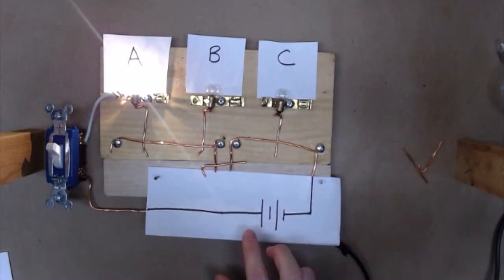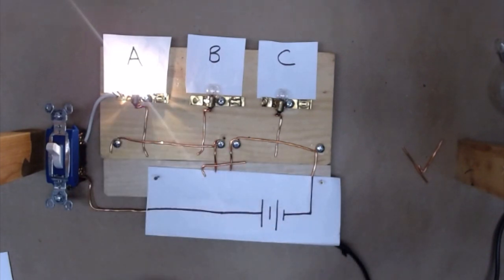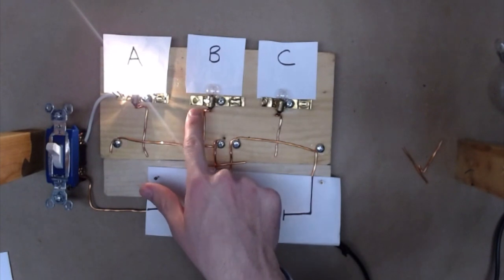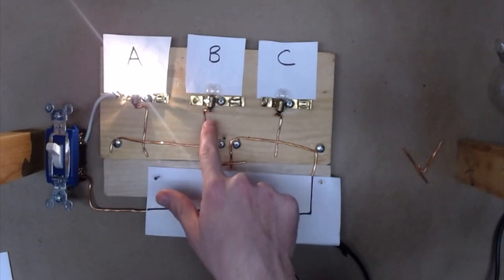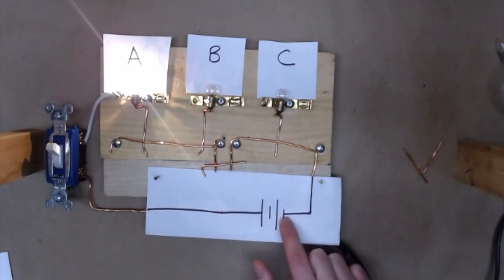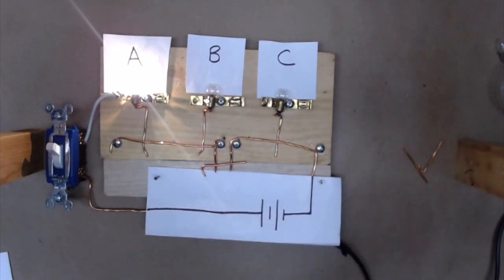So we can see the high and the low potential are connected to bulb A, so therefore bulb A illuminates. That can also help us explain why B and C do not light up. Well, if we go from the high over, up, well, the brass side here, remember it goes through the bottom, through the filament into the brass, is not connected to my low potential here, so it will not illuminate. I need to have both the high and the low. Remember that potential difference is what allows the charges to move.